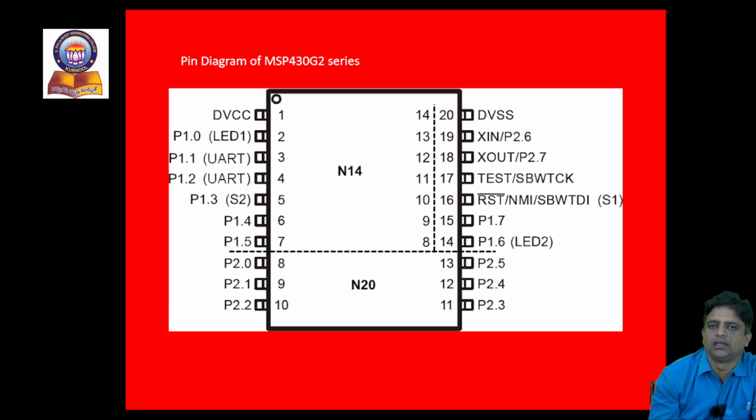Now arrangement is also being classified with respect to the clock arrangements, power supply arrangements, and ground arrangements. Pin number 1 is a supply arrangement where we can have a provision of maximum of 3.6 volts, and still a low power can also be operated with our MSP430 processor up to 1.8 volts of DC. Then on pin number 20, we can see the ground arrangement VSS. In this description, what we focus is how a general MSP430 arrangement is represented.